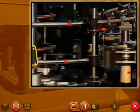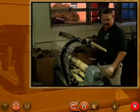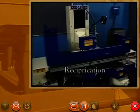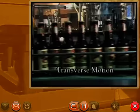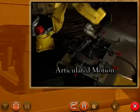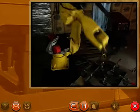In general, it is a machine's movements that dictate the kind of hazards that it presents. All machinery operates using a combination of 3 basic motions. Rotation, moving in a circular pattern. Reciprocation, moving back and forth. And transverse motion, moving in a straight line. When these are combined, they produce articulated motion. This can be especially dangerous because articulated motion makes it hard to anticipate which way a machine's parts will move at any given time.